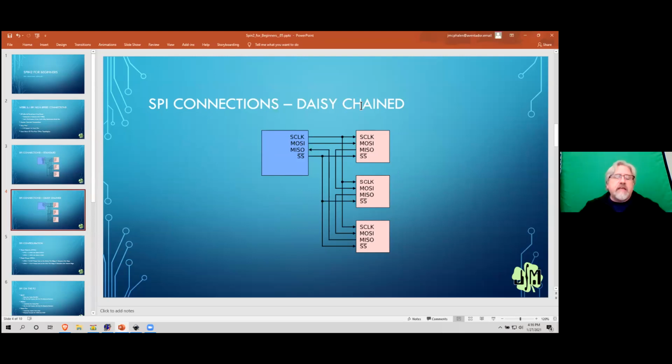The opposite side of that is using a shift register, another really common part called a 74HC595. That's an output shift register. And so with that and a little bit of code, you can take 3 lines and turn it into technically up to 32, which is probably a practical limit that I would ever do. And I did that once for Disneyland, where they needed a whole bunch of outputs from a Propeller board. So we used 595s, and we were able to take a long and shift it out, and that aligned itself into the 4 devices. So with 3 outputs from the Propeller, we got 32 outputs from the 595s.